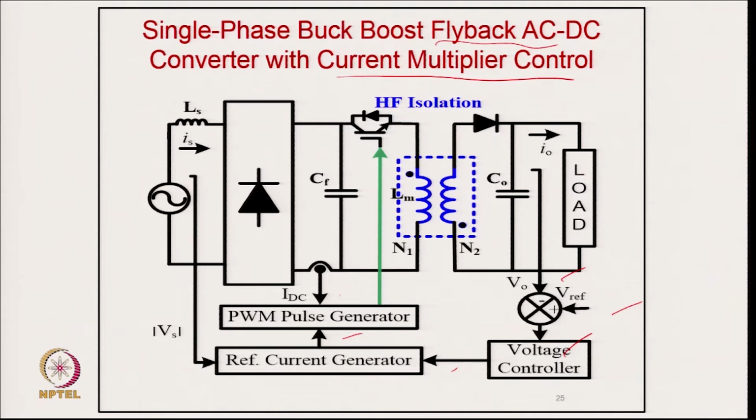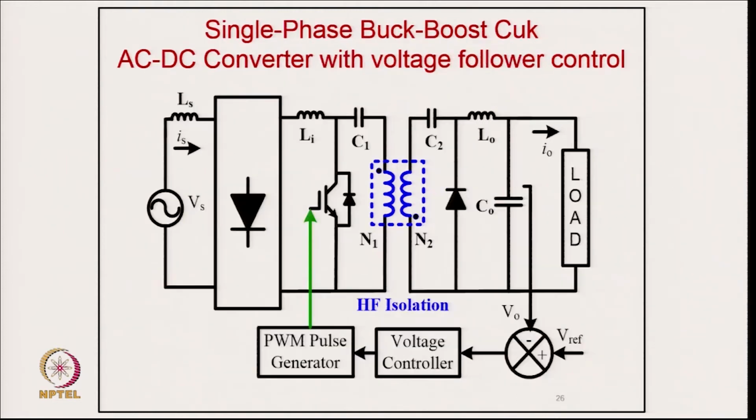This is the simplest converter. It is very extensively used from a fraction of a watt to even 500 to 600 watts. But the major range starts with something like a digital energy meter, at half a watt, where this flyback converter is used as the SMPS, because you can see the minimum number of components in this converter.